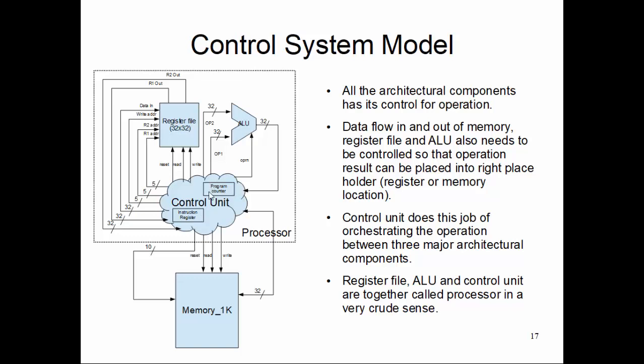We'll discuss the program counter a little bit later in the course, but essentially this holds the address from which the next instruction of the software program will come, because in a stored program model your software program is also stored in the memory, and there has to be a counter which tells me my next instruction's address, so that I can take it out of the memory and execute it.